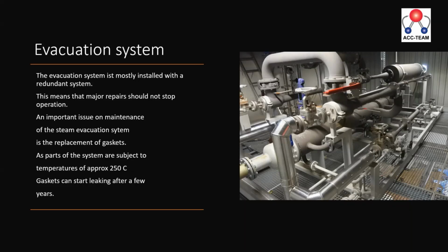They had 3 liquid ring pumps for startup and 2 steam ejector systems for operation. So I told the guy, switch off the liquid ring pumps, because they don't do anything below 150 millibar absolute. So we went to the other ones. Then we noticed that one of the steam ejector systems was completely cold. There was nothing going through. He said, I don't think this system is actually in operation. So switch it off. Instead of 5 pumps, he only had 1 left. We went to the control room and he had 70 millibars. And he didn't know why.